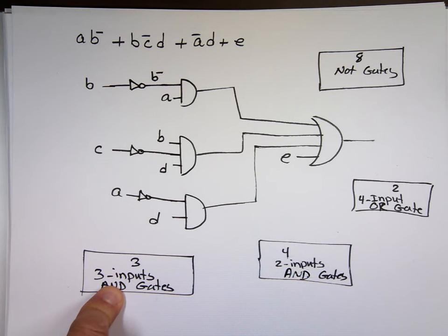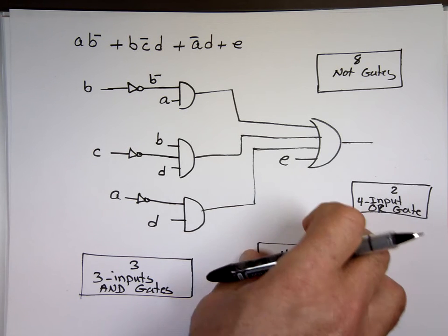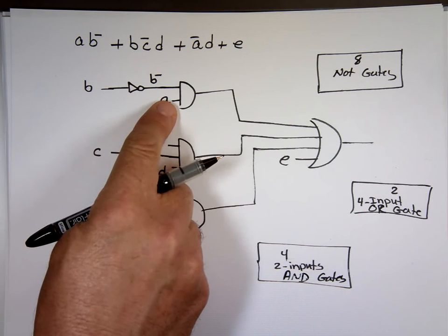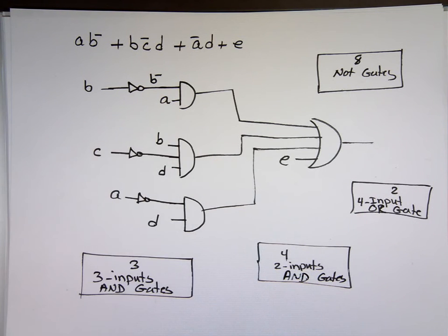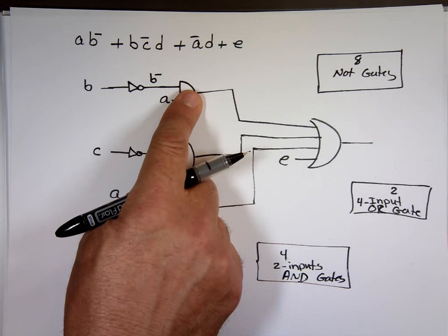You should just use the 3 input AND gates instead. I could actually. Good answer. I could take this one out and say use 3 input. Well, but this one has 2 input. What do you do with the third one? Useless. No, you're going to connect it somewhere. Tie it to high, make 1. If you tie it to high, you killed it because it becomes 1. So I could eliminate this.